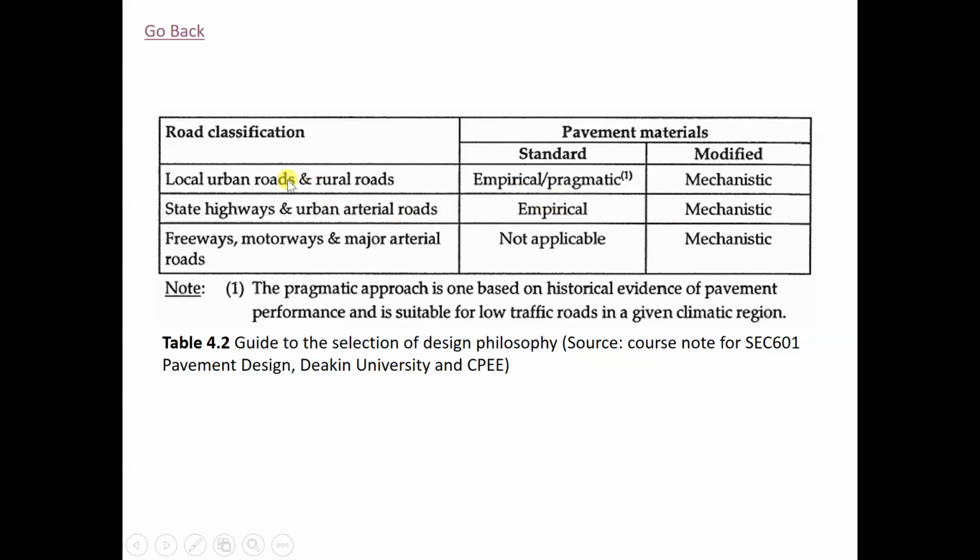I think the state highway here is probably not the motorway, not the expressway, not the multi-lane road, but rather a two-lane two-way road. They could still use the empirical approach. For freeway, motorway, and major arterial road, they have to use the mechanistic approach.